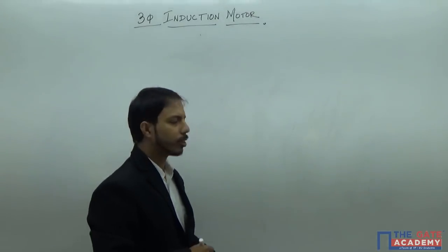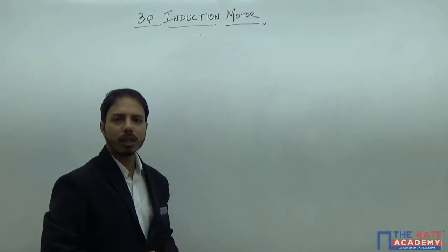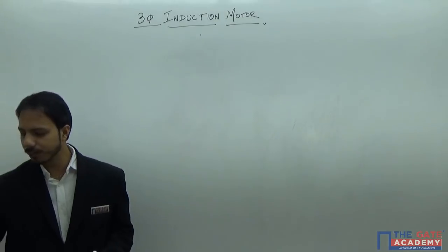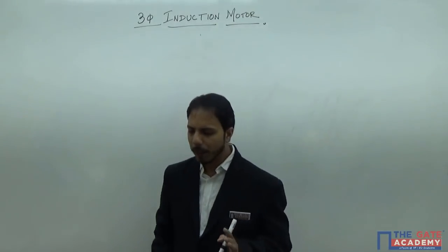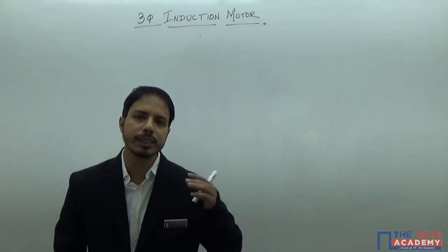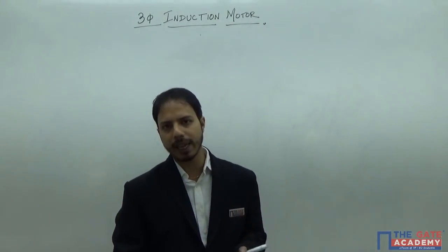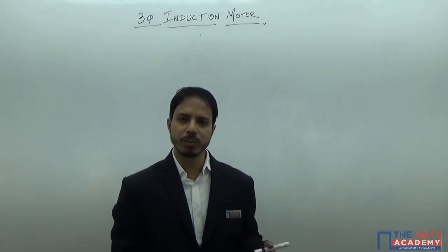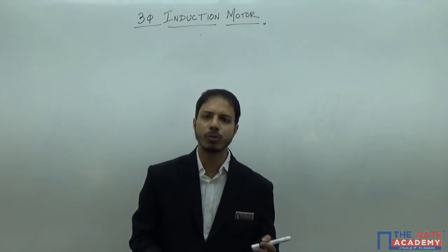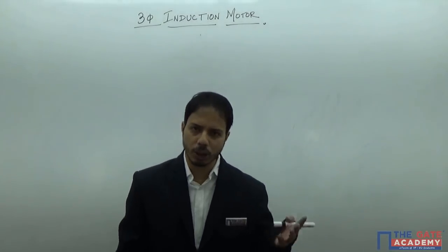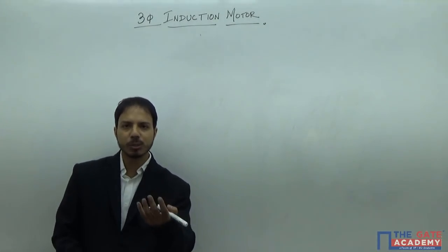Now, the induction motor is all about relativity. We also know that the rotor of the induction motor cannot rotate at the synchronous speed. Why? Because the moment the rotor reaches the synchronous speed, the flux cutting action stops. And if the flux cutting action stops, the EMF induced will be zero. So if the EMF induced is zero, the force experienced will be zero. If the force or the torque becomes zero, what will happen? It will decelerate.